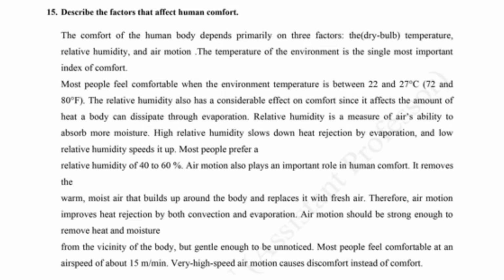The relative humidity also has a considerable effect on comfort since it affects the amount of heat a body can dissipate through evaporation. Relative humidity is a measure of air's ability to absorb more moisture. High relative humidity slows down heat rejection by evaporation, and low relative humidity speeds it up. Most people prefer a relative humidity of 40 to 60%.